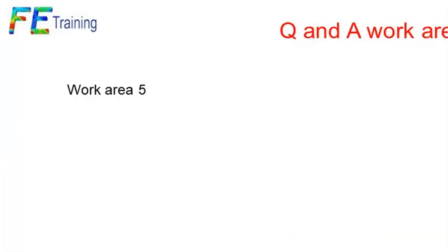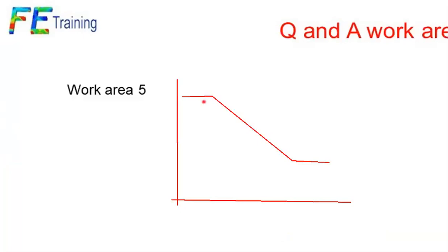So again, using a sketch, I promise this is the last question, David. What we said is we sometimes put a little lead in up to 1,000. You don't really need that. Then this is our main curve. Let's draw some axes in here. This is our stress amplitude, this is our life, and this is the 1,000 value. Beyond here, it's going to be a very, very fast failure. This is our main thing in here.